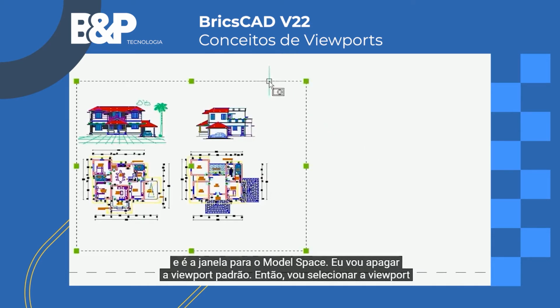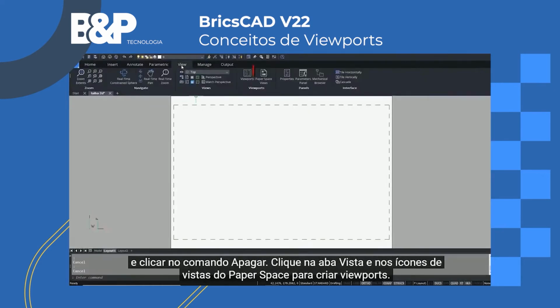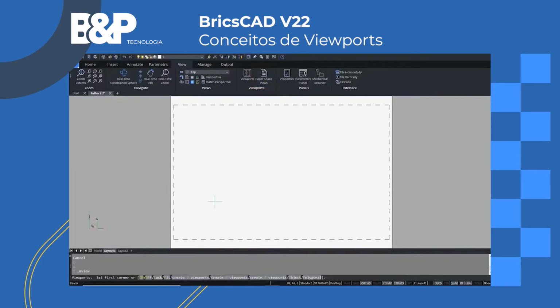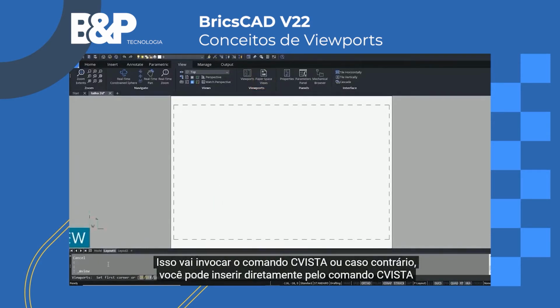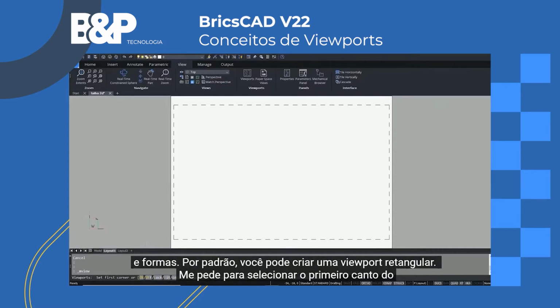I'll erase the default viewport, so I'll select the viewport and click on Erase command. Click on View tab and paper space views icon to create viewports. This will invoke the mview command. Or else you can directly input mview command at the command line. And using this command, you can create viewports in different sizes and shapes. By default, you can create a rectangular viewport.